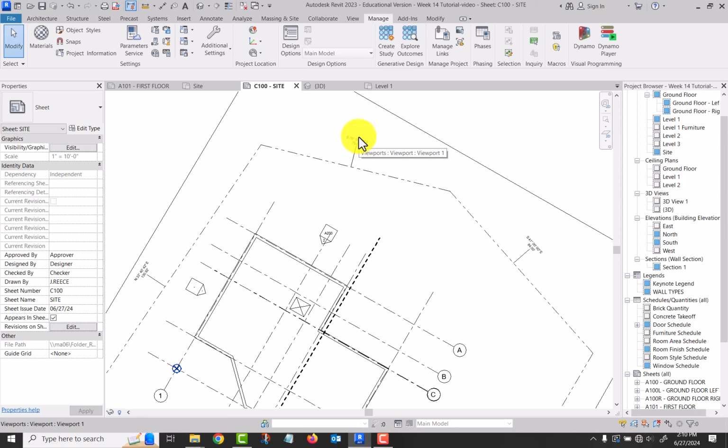And your tags will be adjusted based on that, because if you had looked at my property line tags beforehand, they were based on property north. Now we've established things to true north, so it updates and changes those. All right, so that's about project information, coordinate systems, and orientation. So I'm going to pause this one, and then we'll come back with the rest of it.